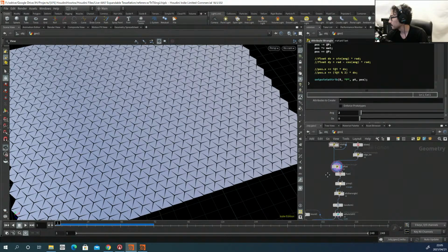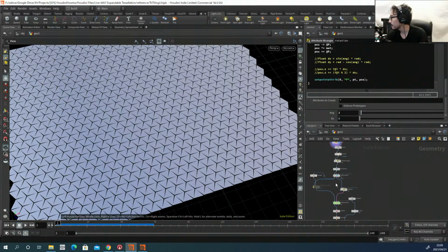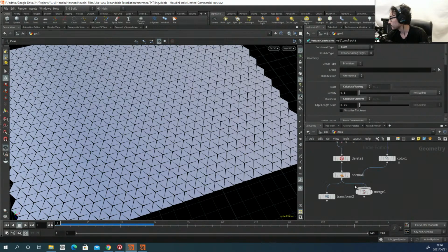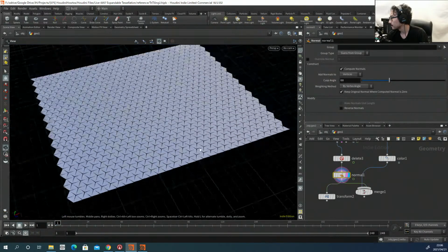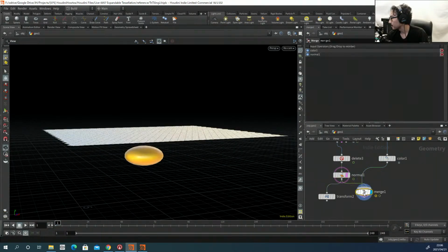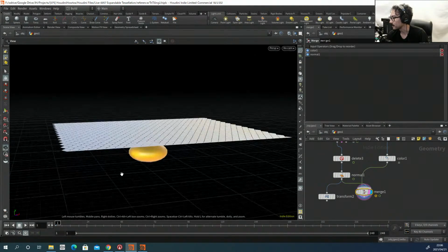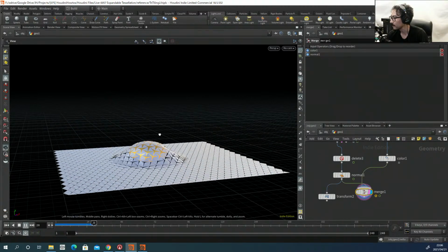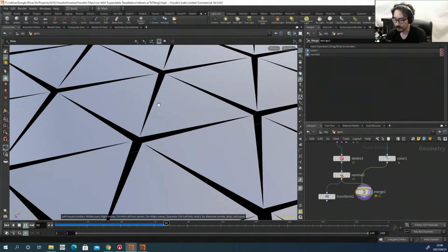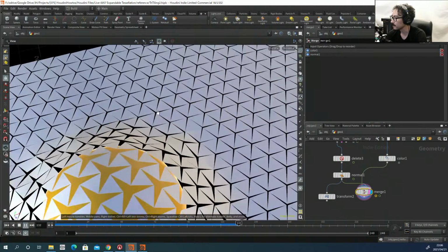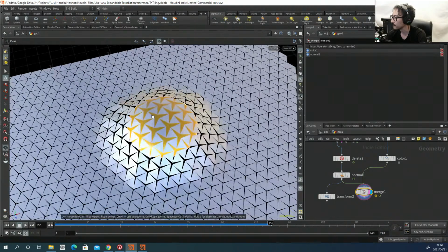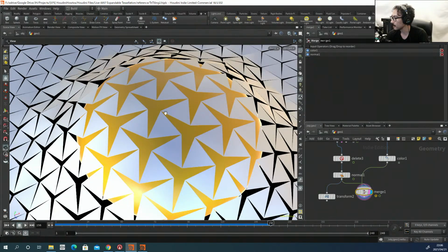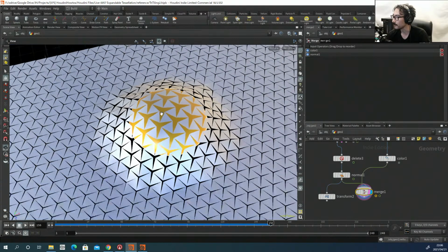Okay, and to do that I am going to use this parametric pattern with Vellum like these to simulate something like a collision between some random objects and see how these patterns will behave based on this kind of interaction with the other object, and see how you can control its openings based on the deformation of the surface. As you can see, the area of the triangle is not changing, just this connection is changing to make these openings a bit larger to be able to deform in this way.